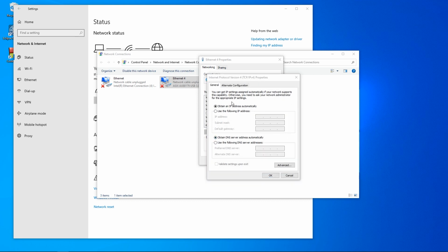Here we can set that a fixed IP address should be used at this interface. For our experimental setup, we have to make sure that the adapter uses the same subnet as the controller. From the information sheet in the starter kit, we can see that our controller is configured to the IP address 172.20.230.120. So we'll assign the IP address 172.20.230.1 for the adapter. For the subnet mask, we take the default values.